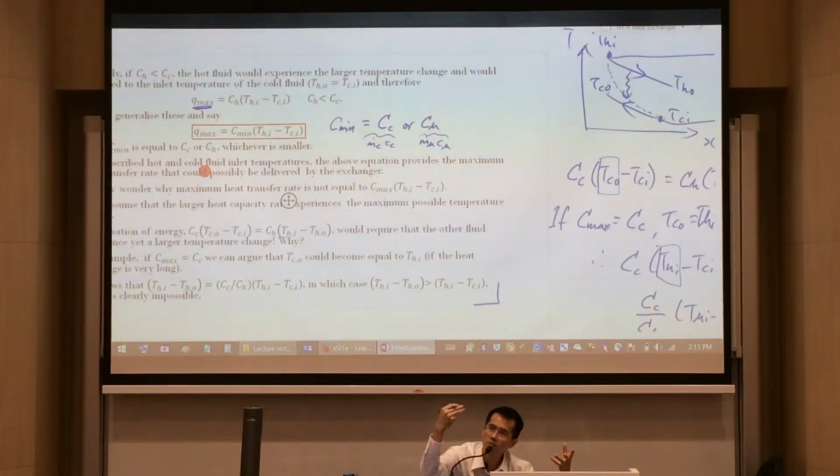If you multiply the mass flow rate and specific heat capacity of each fluid, there will be one number that is higher than the other. The number that's lower is what we call the capital C min. Later on, there will be an example to show you that. So we often talk about C min. If you're wondering what that minimum thing is, it is the minimum heat capacity of one of these fluids. How do I know which one is minimum? You have to take the mass flow rate multiplied by the specific heat capacity.